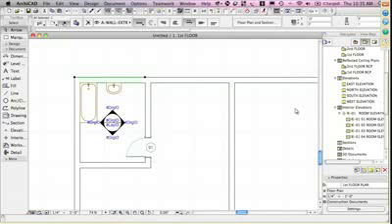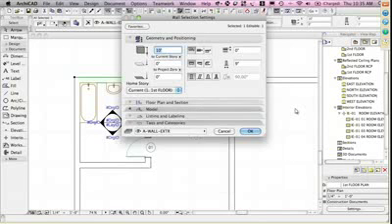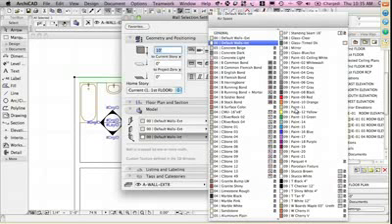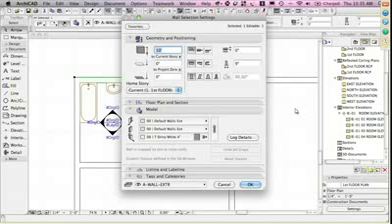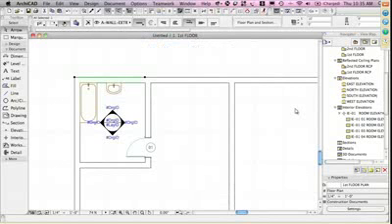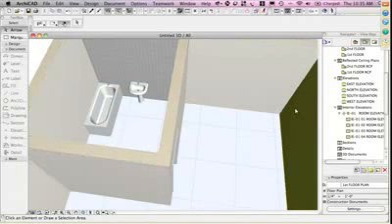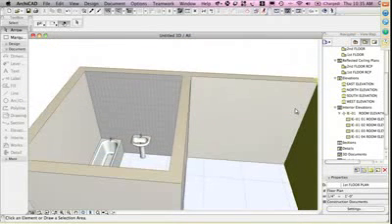And so now I've got a short piece of wall, and if I go to the settings for it, there's the materials for the model on the outside, which is the default walls, interior or exterior, and here's the one for the inside. And perhaps if I pick one that has a tile pattern here, so this is not exactly a match, but it'll just be an example, I'll pick that. So now if I look in 3D, we'll see that there is now a pattern, but it is from floor to ceiling, and her question was, how do I avoid that, or how do I do it more specifically?